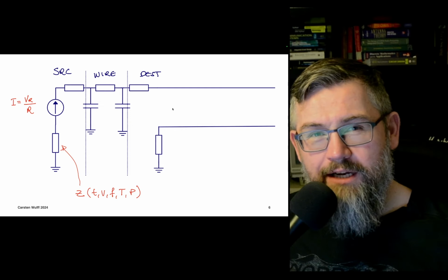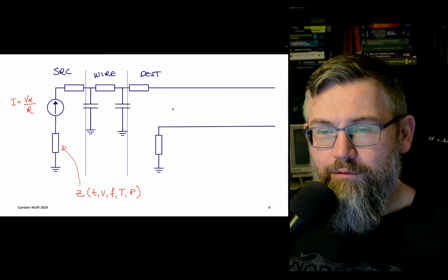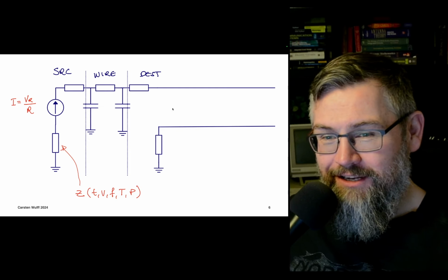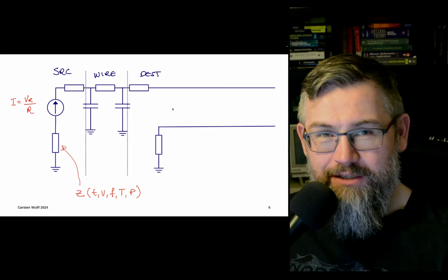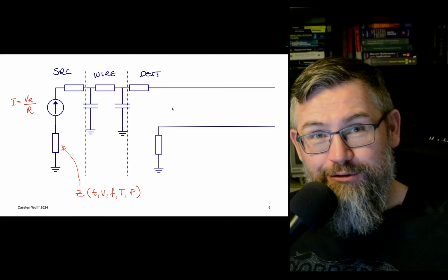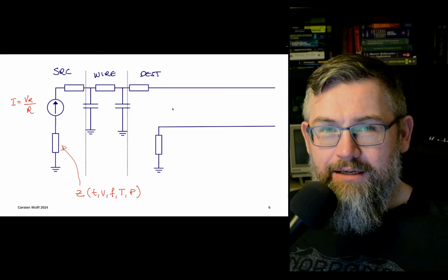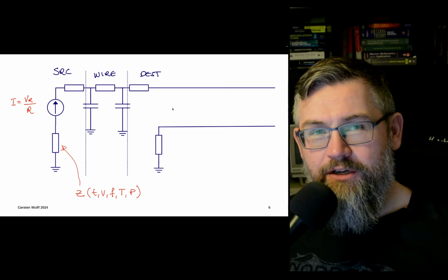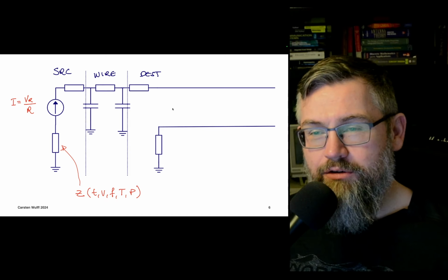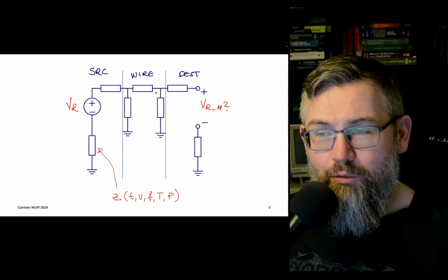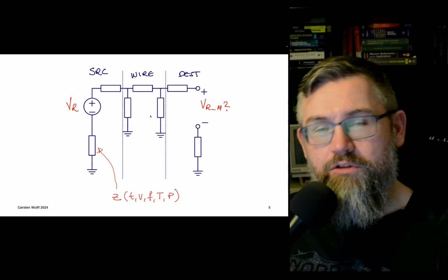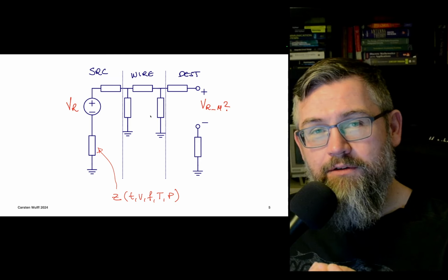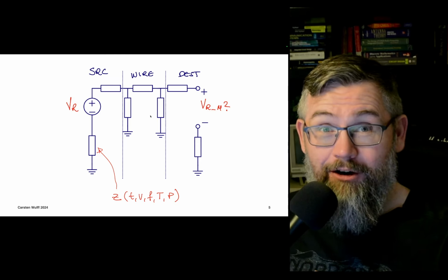But now we're back to a catch-22. I said that in order to distribute voltages accurately across the chip, we should do it in the current domain. But now I'm saying, don't do it in the current domain because you can only get plus minus 2% accuracy. You should do it in the voltage domain. These two things sound like they can't both be true, but if you need a precise voltage reference in a battery charger, then you can't distribute it across the chip. You need your bandgap or your voltage reference circuit to be right next to where you need it. That's the only way to make it really precise and get that 0.5% or even better.